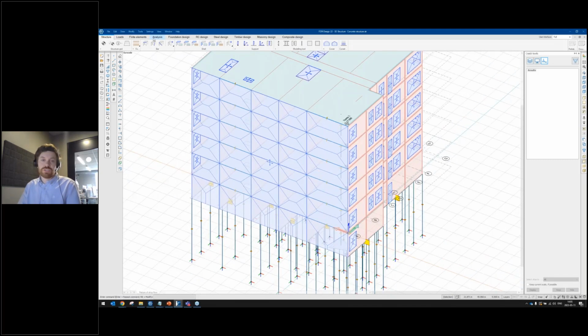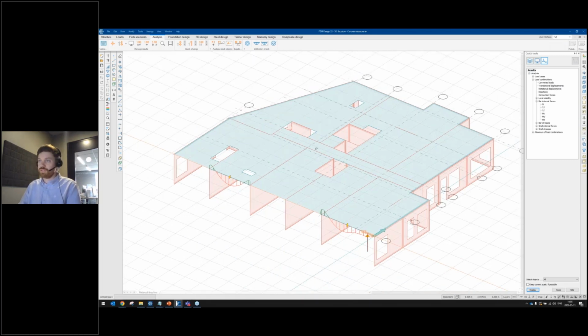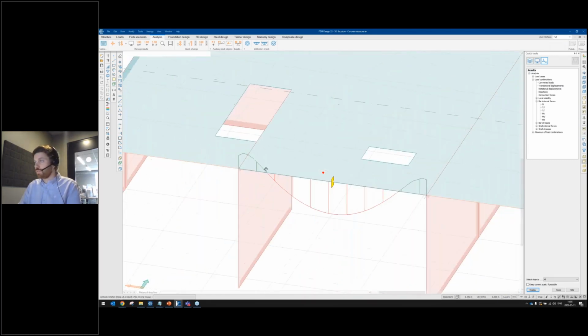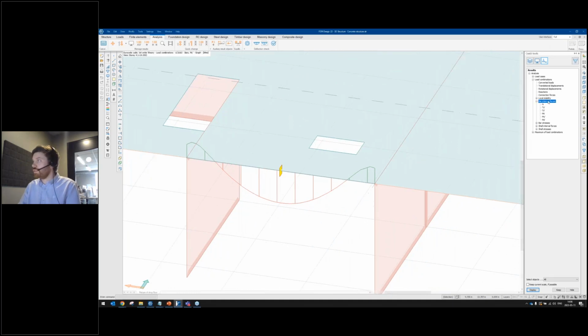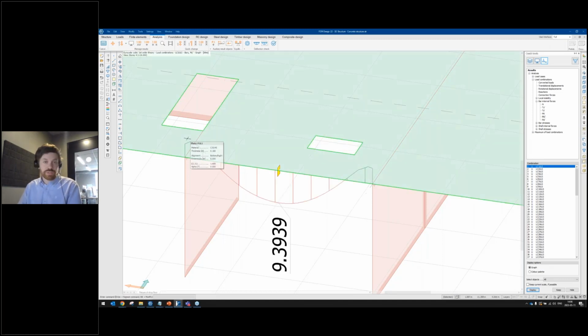So let's first start with the moment and shear reduction zones that are new in the new FEM Design 22 version. Let's switch over to the analysis tab and take a look first at the moment. This is the moment for the internal force for the bar. If we take a look at the moment here, let me just rescale the view here, 0.1 is good. We can see the moment distribution without any reduction for this bar.